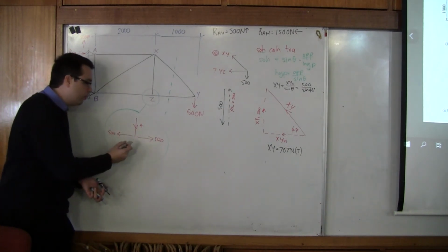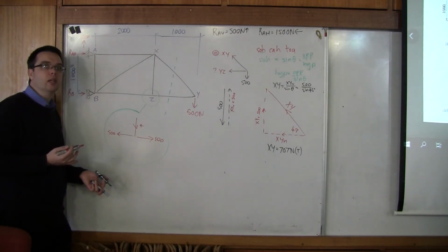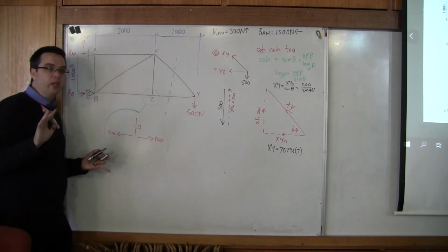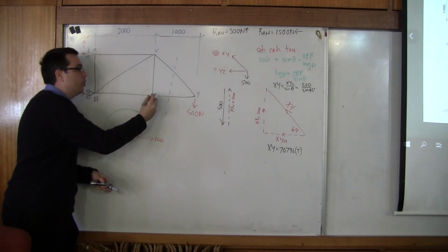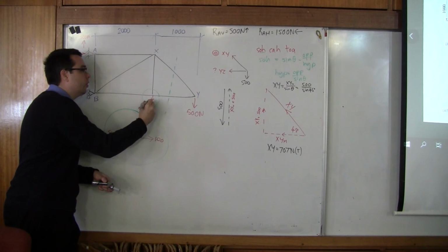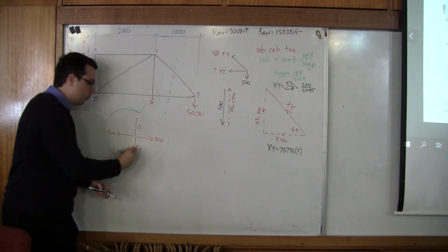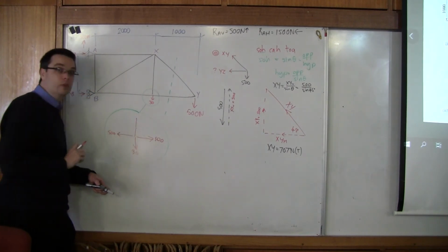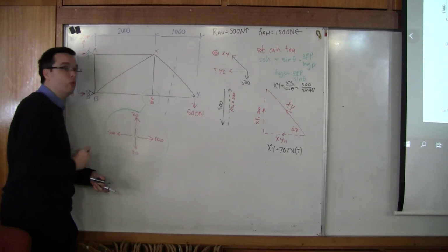There's nothing that could balance. There's nothing that provides an upward force to balance that. So therefore, the only number that is acceptable there is 0. Now we're just going to imagine, in imagination world, that someone put 30 newtons here, an external force of 30 there. Now what would happen? There would have to be 30 going up in order to balance that force.